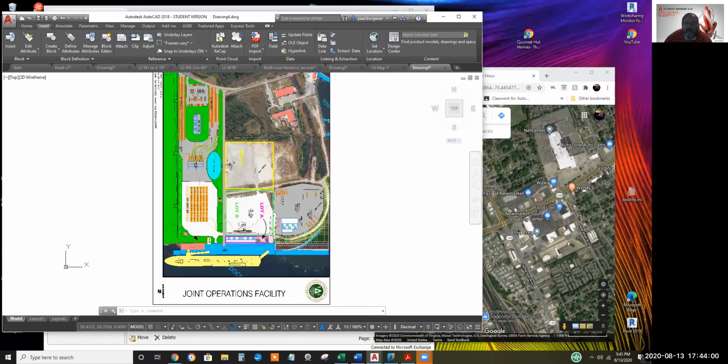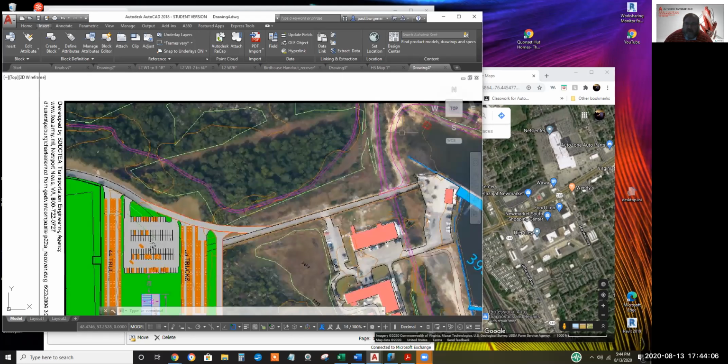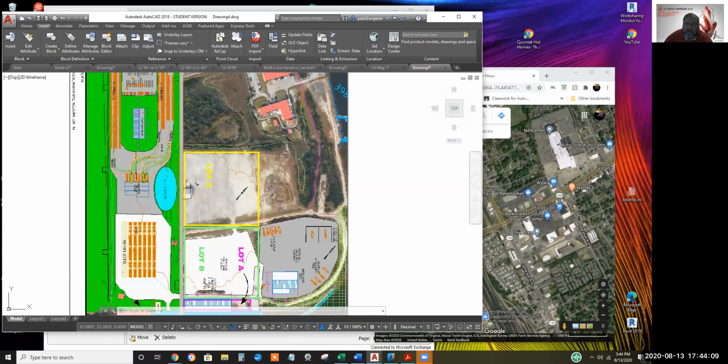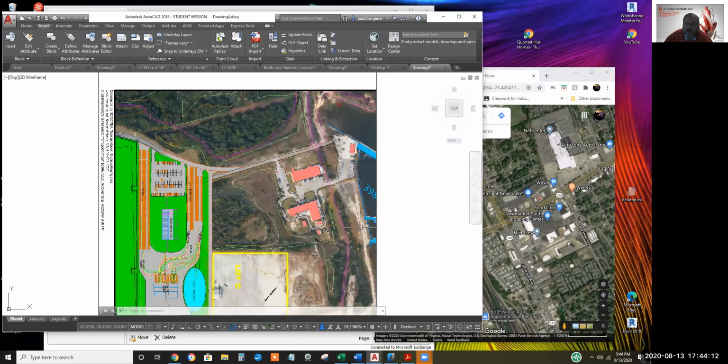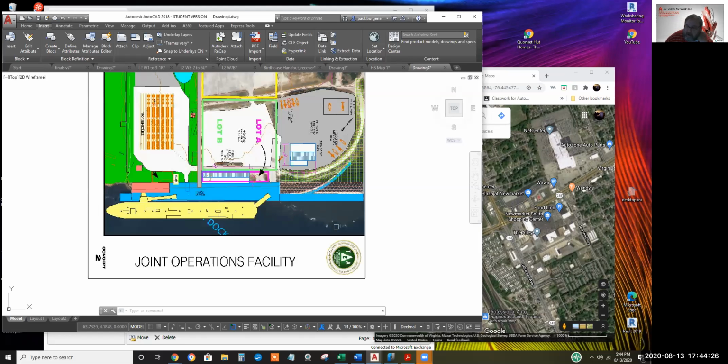This is taking a lot longer than I thought, but anyway, by capturing an image off the internet that has a bar scale somewhere in it, like maps.google, where the bar scale is in the lower right corner, so include the bar scale in the lower right corner. With the scale command's reference option, you can enlarge the image so that the bar scale is accurate, so that you can click 2 points with the distance command and it'll tell you the number of feet between those 2 points. If you've got the bar scale showing 1,000 feet is this length,